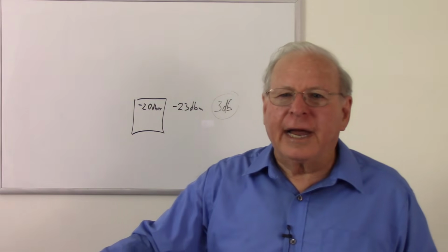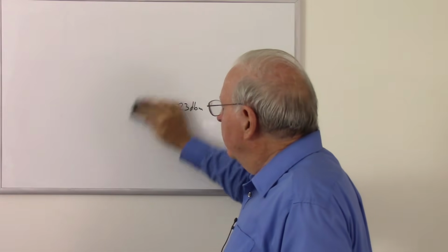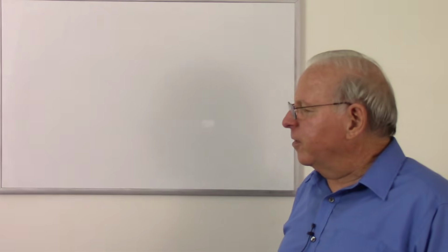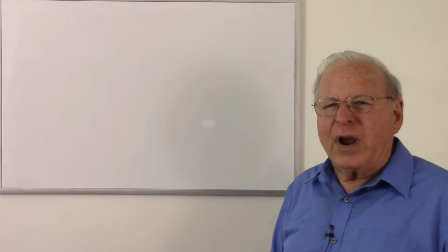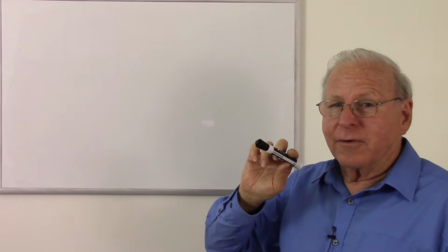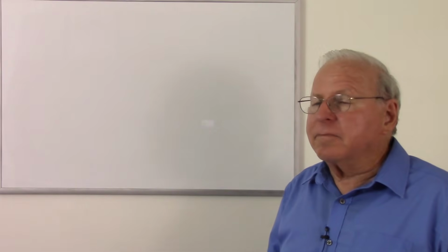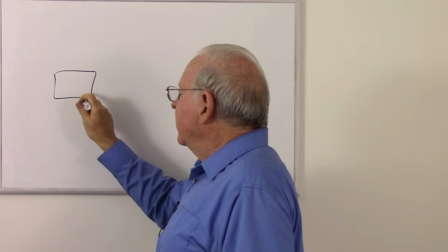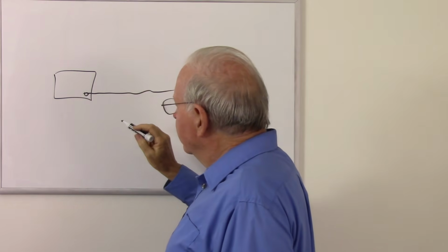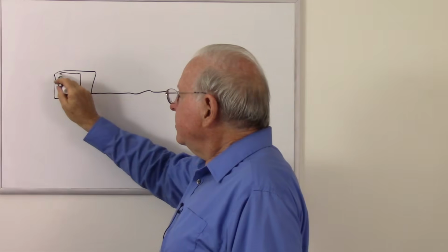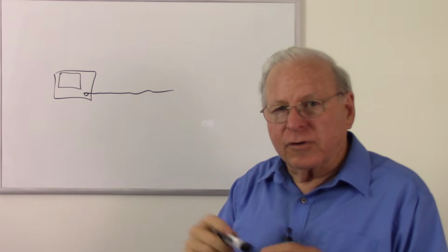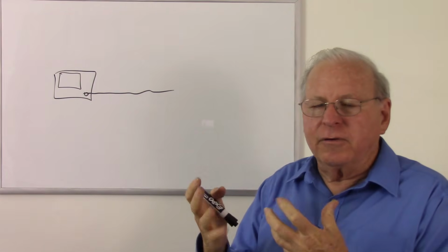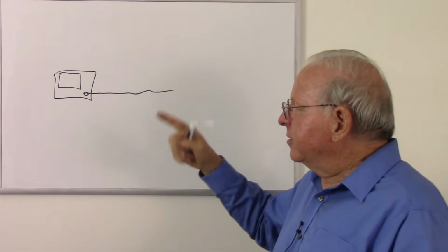So another thing that you might hear about or see, who knows, is the OTDR, the Optical Time Domain Reflectometer. Ooh, fancy word for this device. It's basically radar that sends down, maybe LiDAR if you want to be correct, sends a pulse of light, laser light presumably, down the fiber. So here's our OTDR. We connect a fiber to it and it goes wherever it goes, and we have a display on it. And I used to like to use one that was an old analog one with the CRT display, because once again you get a feel for what it's telling you. And then we would give them a more modern one which gives a digital display.